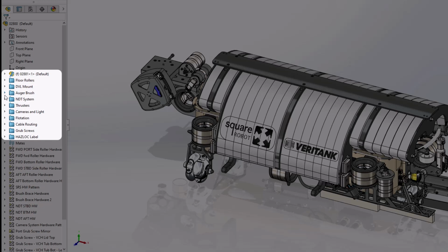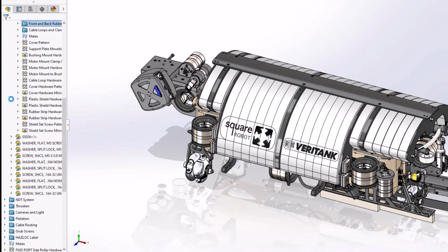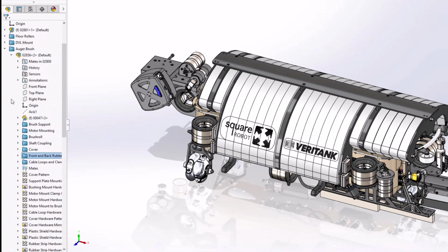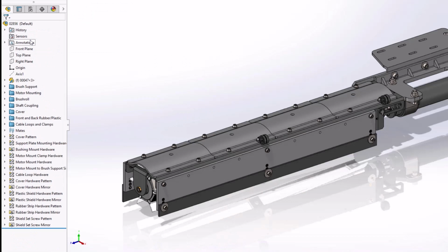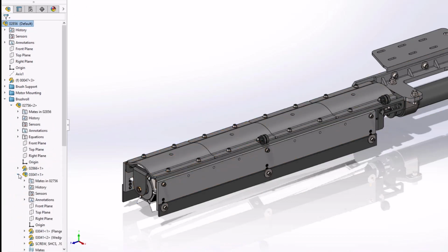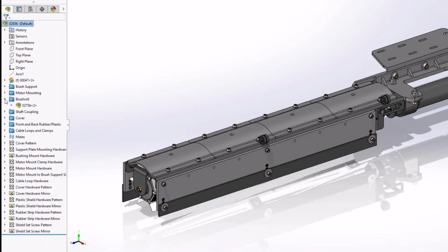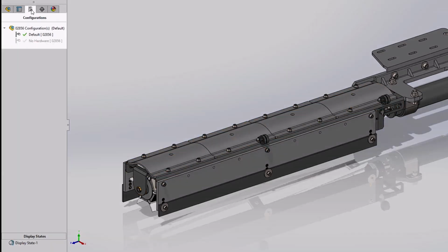To improve working with lightweight components, there is also a more streamlined approach to accessing the assembly and feature information. Simply expanding a component from the Feature Manager tree will now dynamically load those components on demand, giving us full access to resolved subassemblies and parts. This prevents unnecessary loading of large assemblies, but allows us to quickly access and resolve the components we're working on as needed.